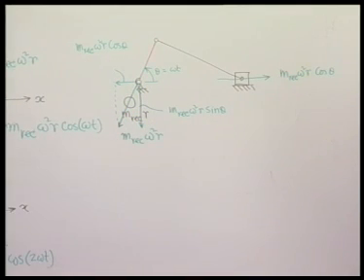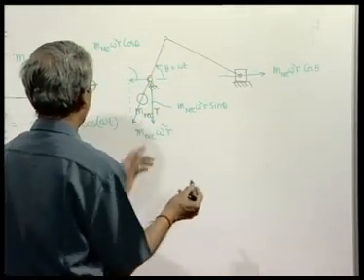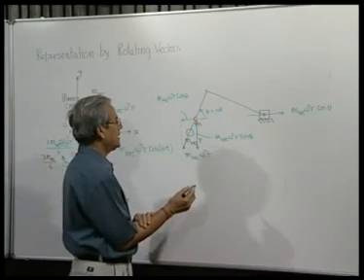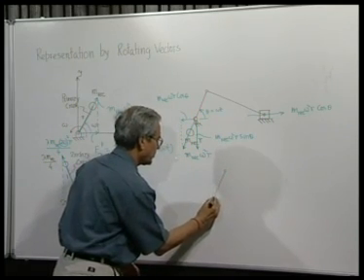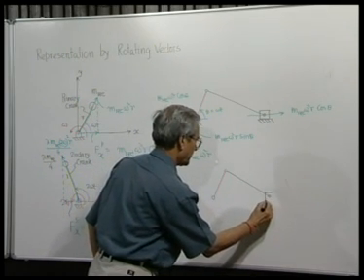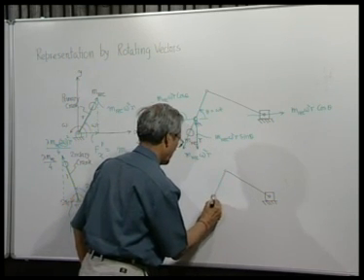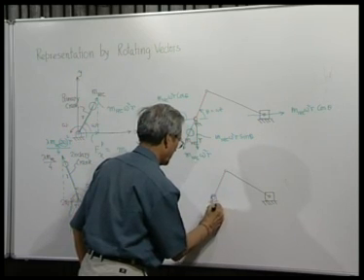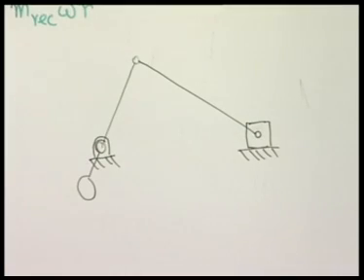Now, the actual original unbalance due to the reciprocating mass and the centrifugal unbalanced force produced by this balancing mass attached as a counterweight, in effect, the resultant system will be now subjected to an unbalanced force which is in the y direction.